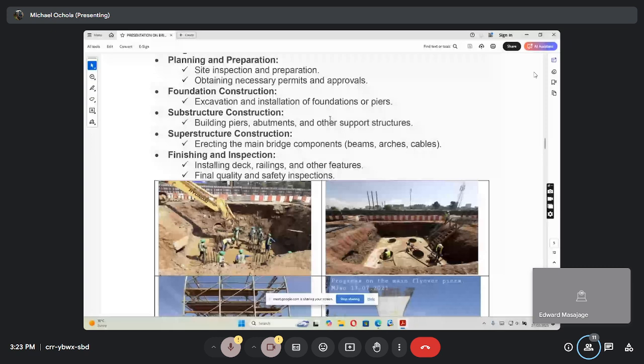The yard, you can see a mold here for each of these girders. This is the mold where, once you have done reinforcement, you put a mold and you cast concrete. This is how the concrete looks. Now, this is where you put the concrete up using these overhead gantries. You place these girders. There are, I think, 4 in number. Put them, and then now you work on the slab.